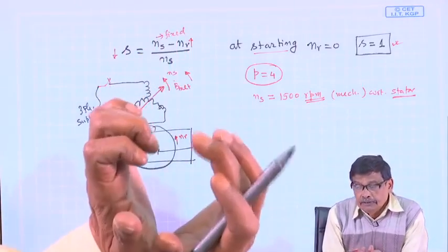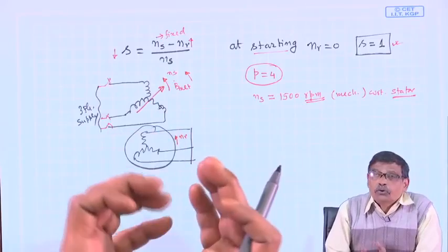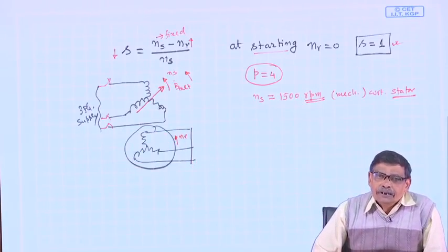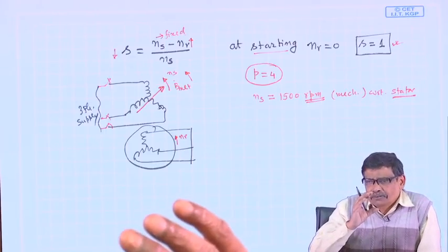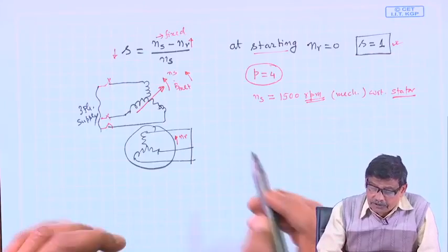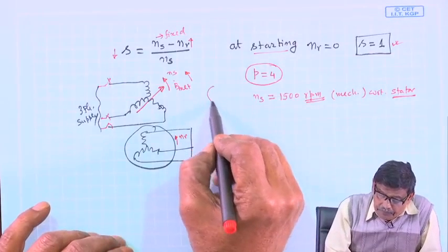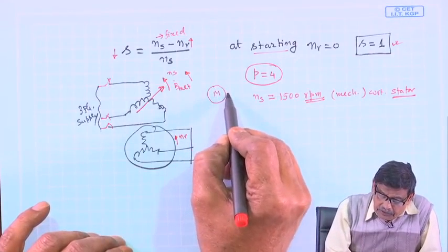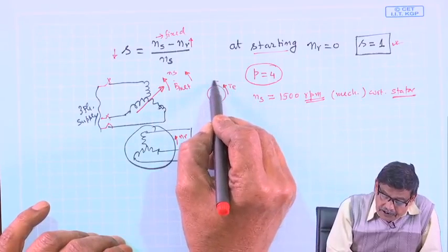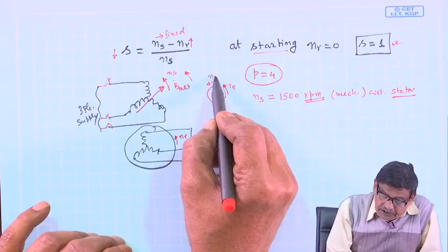So, rotor will then accelerate. Whether that torque value is changing with time or not, it is a positive torque. Recall this diagram for a motor. If this is T, your direction of rotation is also in the same direction.